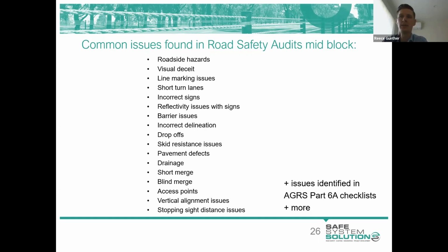Once again, there's a checklist which is really useful in doing your audits. You should always refer to that because it's very easy to become narrow-minded or focused on one particular aspect, which may be motorists, and not focus on all the other road users out there or other hazards that may be present. So I encourage you to use those checklists in your audits, as well as diversifying your audit team. Don't have an audit team that has similar skills.